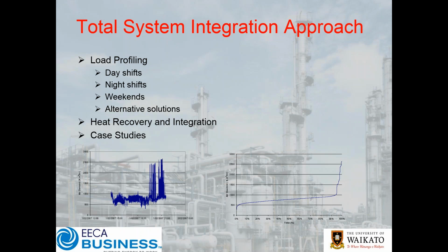Generally speaking, in a retrofit situation, my general feel is that in most instances, you'll probably struggle for the energy cost alone to pay for it. Because if you've got valves already in there that are kind of working, you've got to pay for the full cost. Now, on a new build, if you change the specification, the marginal cost becomes a no-brainer. On a retrofit, what you'll probably need to look at is the additional spillover benefits.